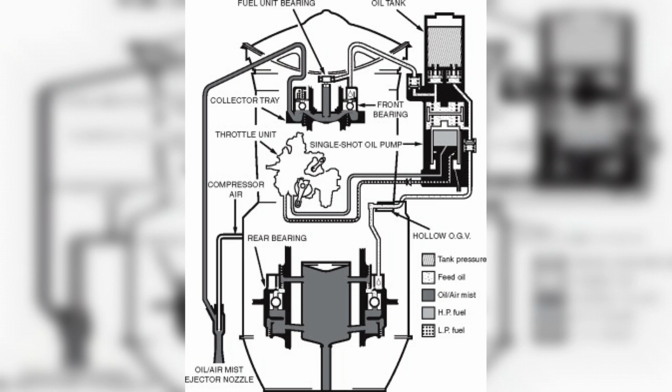This makes it possible to reduce friction at the cold start stage, which significantly increases the overall life of the motor. In winter, in severe frosts, oil becomes thicker, so before starting the engine, the liquid in the tank, main oil pump, and main line is heated by a special liquid-type preheater through a coil with preheated coolant.